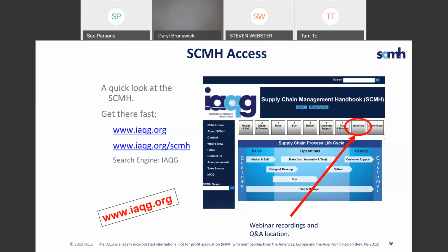For a new project, is a PFMEA needed for each service, or is it global, created by the project leader? For a new product, you need a product PFMEA from basically when the material is received in the door to when you ship it, as per 9145. You can use similar PFMEAs to start from, if they're done well and solid. So you do need a PFMEA for everything.